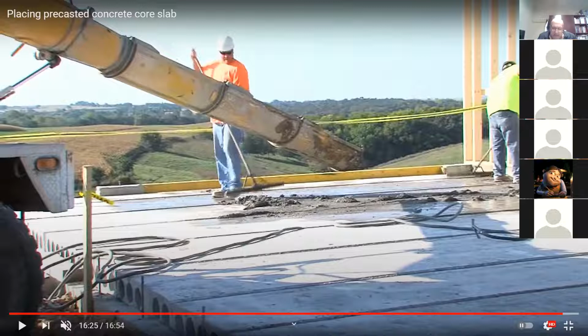For this expansive soil, there are certain precautions. For example, when we design for an area with expansive soil, we do a cut-off wall. On the perimeter, we do a somewhat deep foundation, going 5-6 feet, sometimes 3 feet, depending on the expansiveness and properties of the soil. In many cases, we also add lots of moisture before construction, right before you pour the concrete slab, so the soil expands to its maximum size. And then we pour the concrete right at this point.